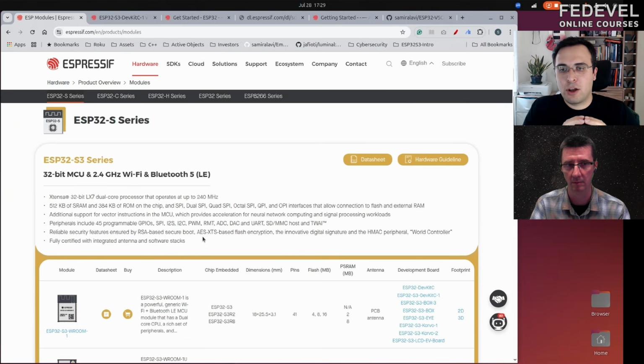For example, when a Wi-Fi station device is connecting to a router, at that point, BLE advertisement might not work. Some tricks are needed, and you need to know as an application designer that you need to prioritize in those situations. This makes development of Wi-Fi applications and BLE applications a bit complicated.